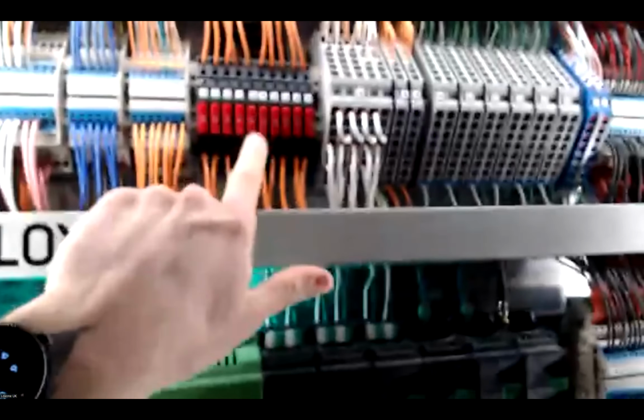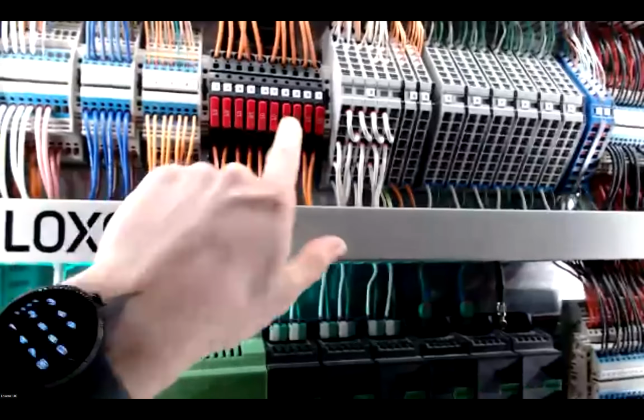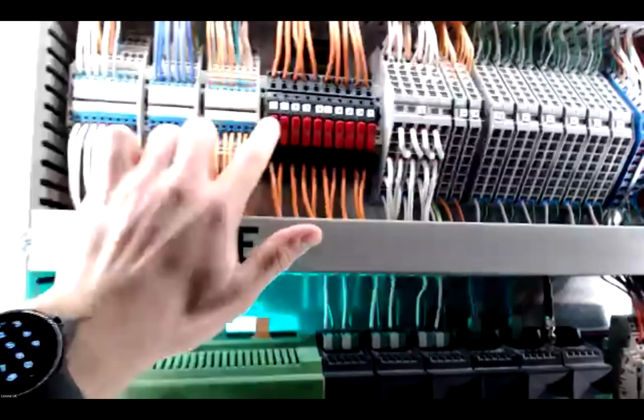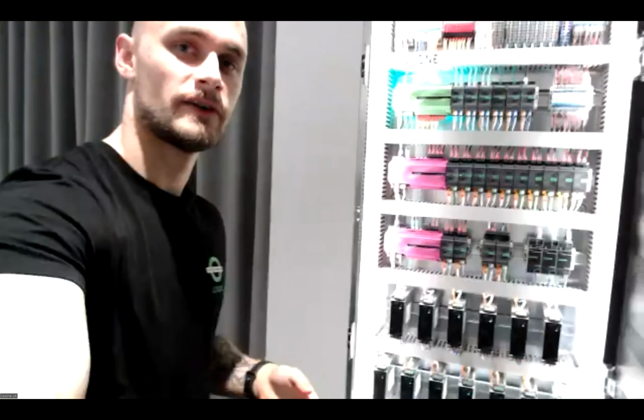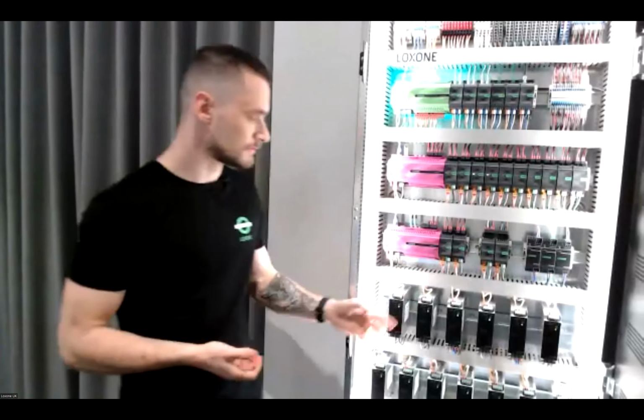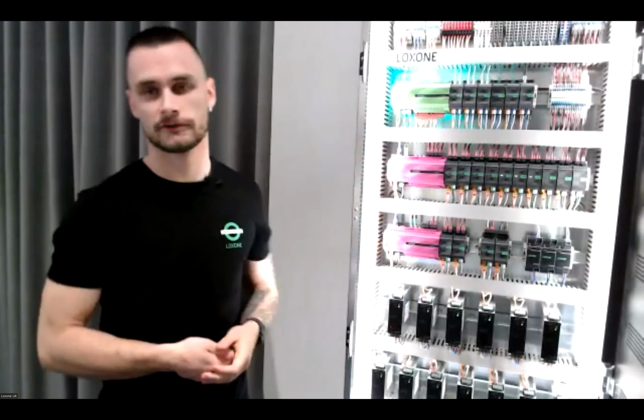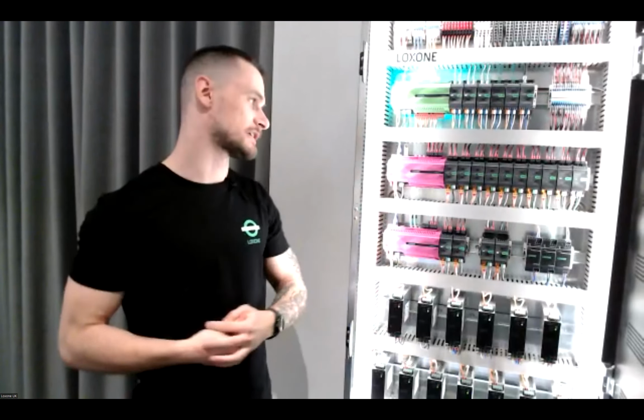Now, the only thing that I can say about this one is that we have them fused, but we have them fused with 10 amp fuses. Well, we already have them connected to 10 amp power supplies, which means that in our case, it's not as necessary. Again, it's a good idea, just in case, for whatever reason, we output more than 10 amps from any of the supplies. However, you shouldn't have to. You have a 10 amp power supply, you have a 10 amp fuse. The power supply is going to do the protection on its own.